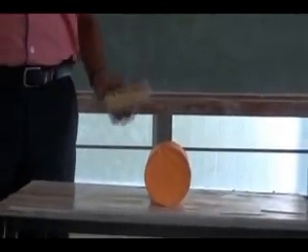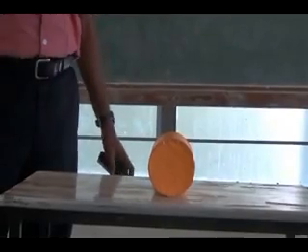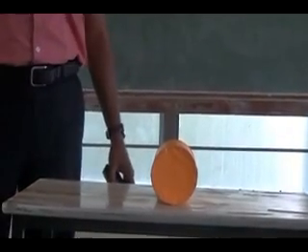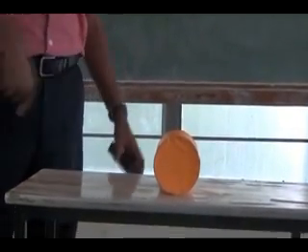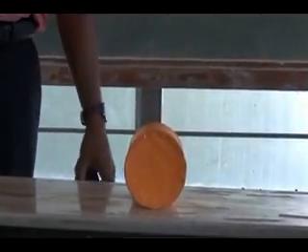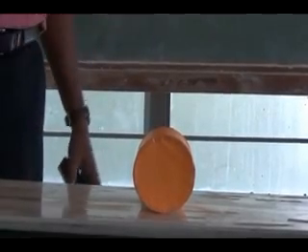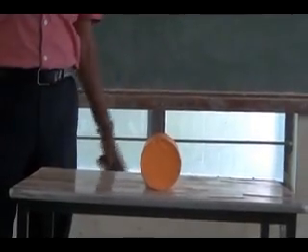You have to draw the projection for this, where you will have the base circle on VP. So touching the reference line, you have to draw the circle. Draw the circle first of all, then draw the reference line touching tangentially to that, right? Then you get the top view. Divide the circle into 12 divisions.